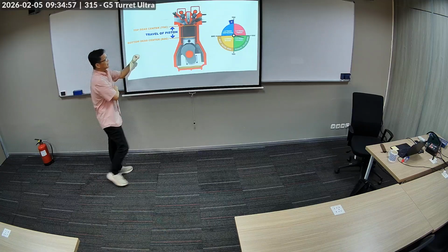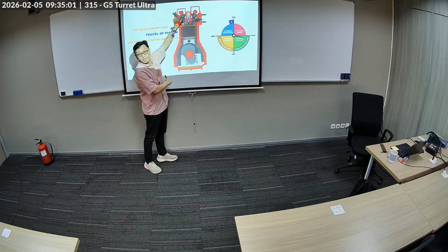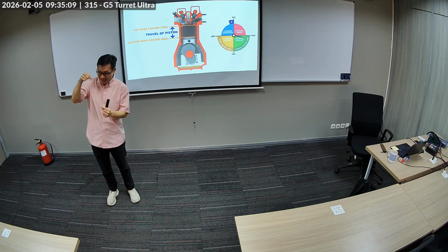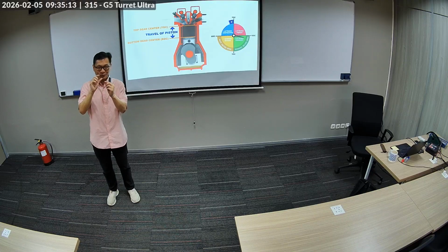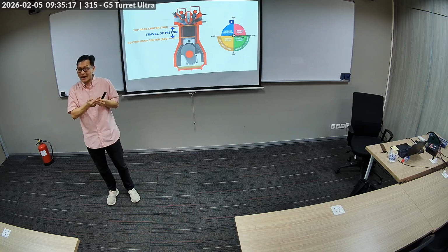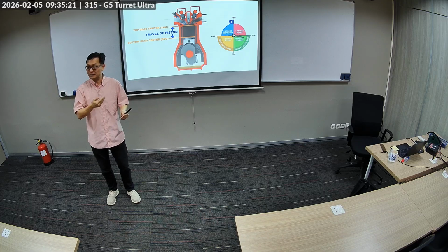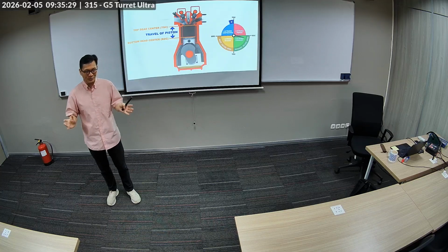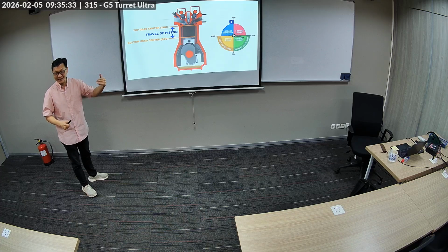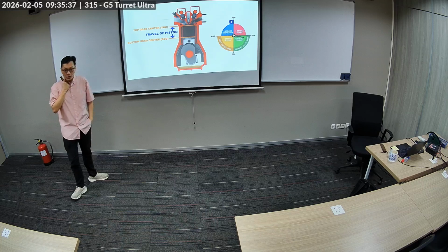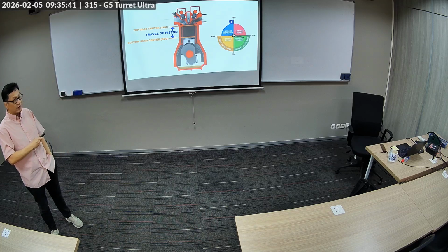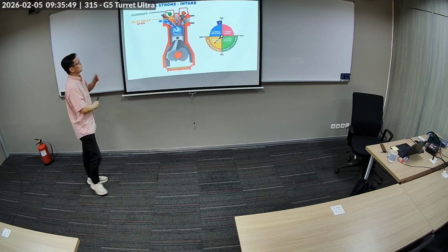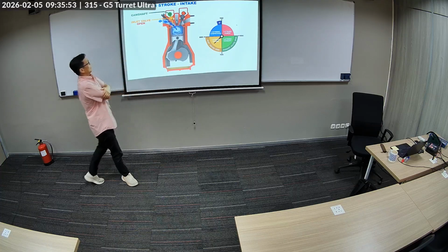The other thing that limits the maximum RPM is this spring. The valve stem will start to float, because see, it also opens and closes like that, right? At one point, the valve doesn't have time to sit back on the spring, it's already pushed again by the camshaft. So the valve has to be lightweight, and the spring has to be stronger while not breaking everything apart. So that's a challenge in increasing the red line. But for most people in car modification, when you want to increase the red line, the first thing you tackle is the head, basically camshaft and valves. You upgrade those. Okay, so they open intake.